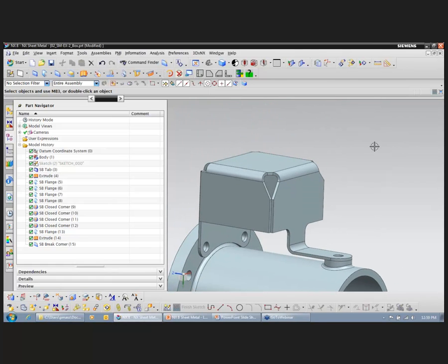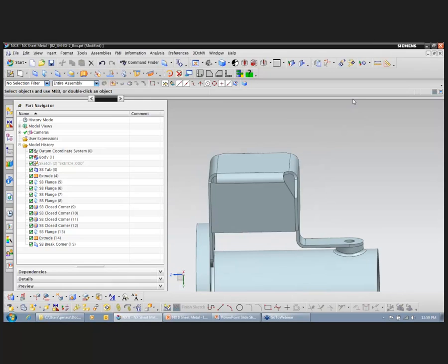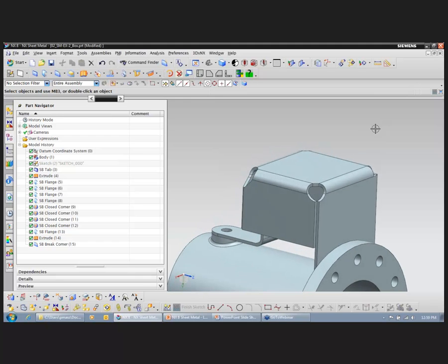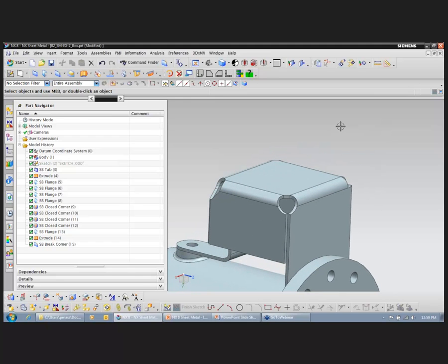So at this point, our bracket is looking pretty good, looking pretty sturdy. Didn't take much effort at all on our part. But maybe the component that sits on top of this bracket needs some type of clearance through this back face and this top flange. Maybe it has some hosing that attaches to the bottom of it or something like that. We need to create a cutout there. For that, I can come in here and use the normal cutout command.